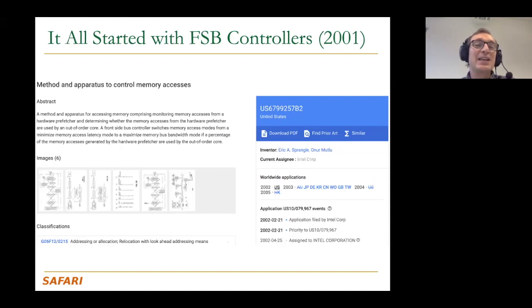Whereas if you bake your memory controller into your processor chip, now you're working with a single type of memory, or with n types of memory where you designed your memory controller for those types, right? But of course, today, there's only one type of memory a processor chip can work with. So you design it for one, because it's hard to do that, because you need to design the physical layer to actually communicate with the chip.